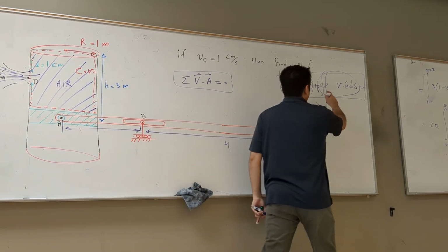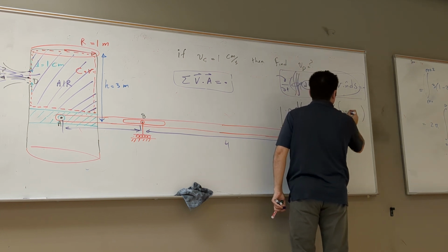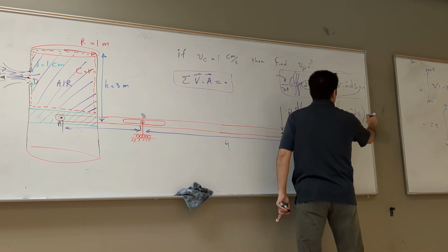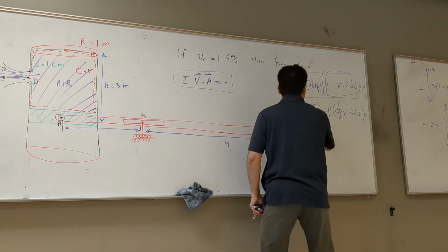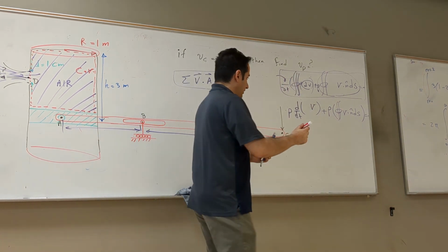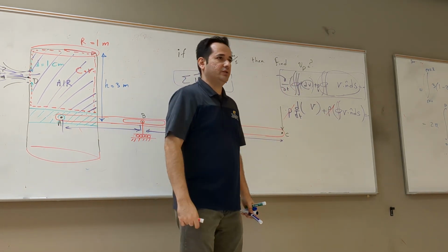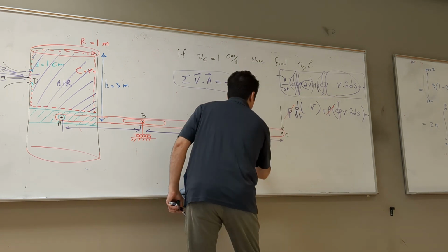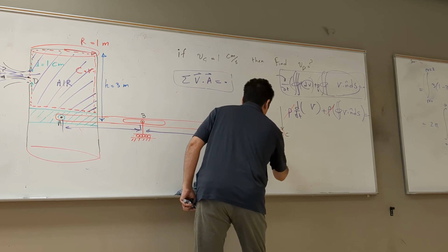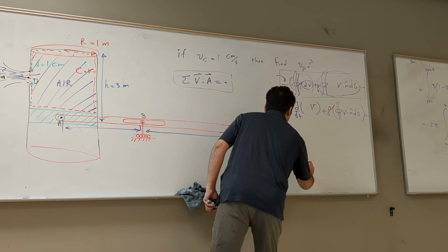So plus, let's do this integral. There is a rho inside this integral, v dot n dS, is equal to 0. Now, your equation is simplified to that. Now you can see I got rho on both sides, right? I can get rid of it, rho is just cancelled out, divided by rho. It just cancels out. So what do you get? dV/dt plus surface integral v dot n dS must be 0.